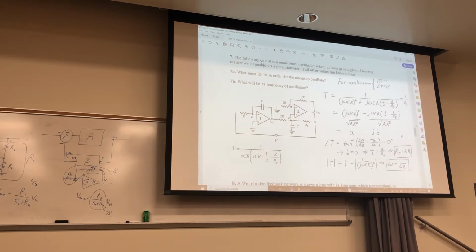Thank goodness. So you have to calculate it. Now the S, that's j omega, so this is a complex number here and here. So it's just rewritten right here. So this right here is the same equation as right here. And I'm going to call this stuff on the bottom A. Okay. What you could do is multiply top and the bottom by the conjugate of A.